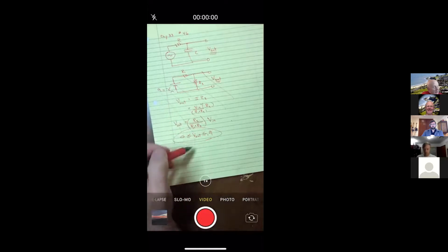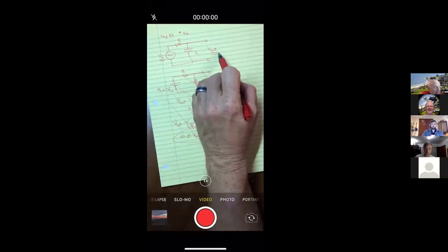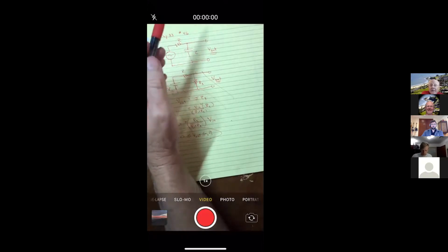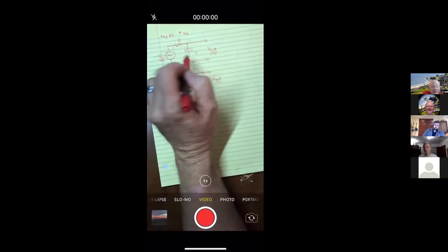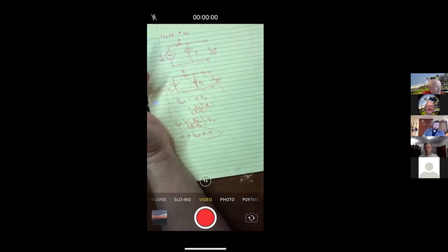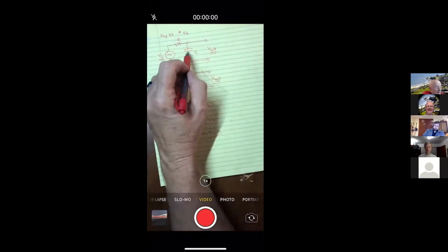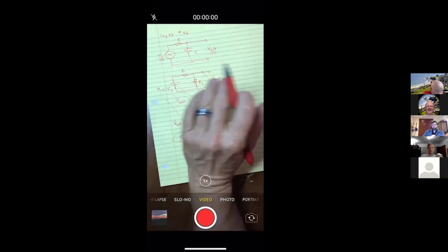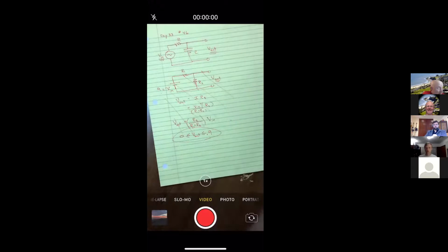Let me cross this out. I'm hoping you'll see that if I call this the voltage in, then I'm going to get some voltage out that is some kind of parameter related to voltage in, but it would depend upon the capacitor and the resistor. And what's really neat about this, and why we call them filters and not just voltage dividers, is because the amount of voltage we get is very much dependent on the frequency. Because remember, unlike this resistor, which just has a value that depends just on the resistance, this has a reactance that depends on the frequency. That's the neat thing about capacitors and inductors, is that they depend upon the frequency.